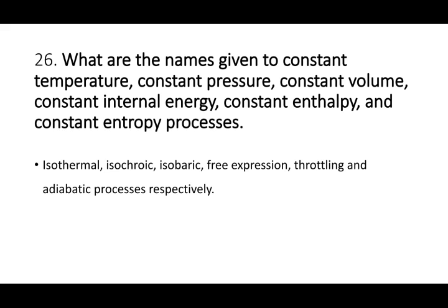Then the constant pressure process. So the constant pressure process is also known as isobaric process, in which the pressure will be constant. Then constant volume process, that is also known as isochoric process, in which volume will be constant. Next process is constant internal energy. This is also known as free expansion process. Then constant enthalpy, this is known as throttling process, and constant entropy process is known as adiabatic process. So these are nothing but different thermodynamic processes.